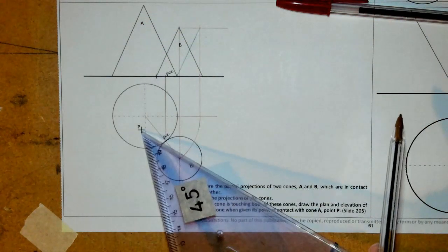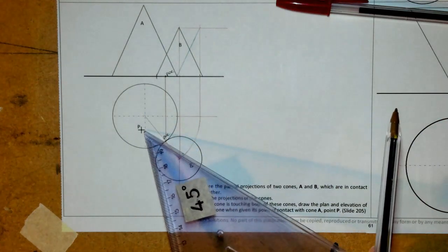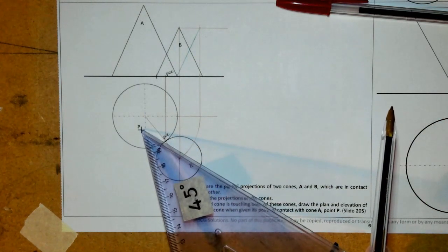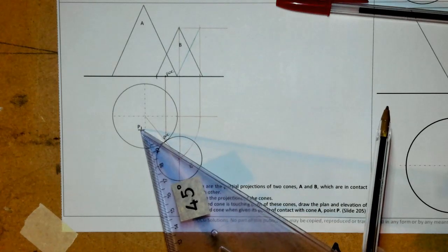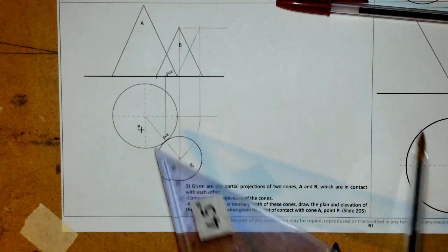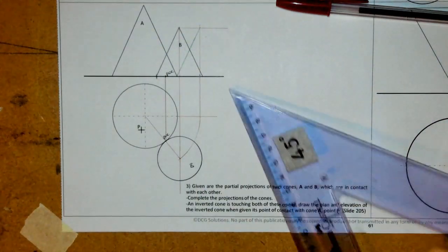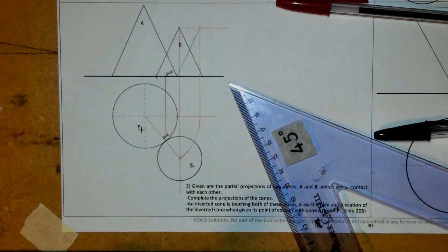They have given us the point P, which is its point of contact, okay? So I'm going to assume that point P is actually where the top of the cone is, or in this case, the base when it's flipped up, and that's the height of it. So what I'm going to do is I want to find point P in my elevation view, okay? So we're going to take a horizontal cut for point P. I'm going to take a horizontal cut. So what that involves,